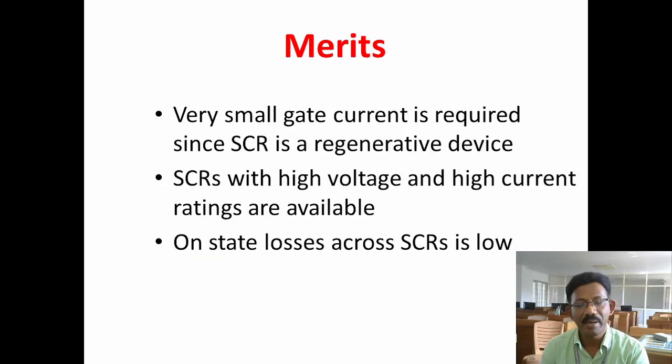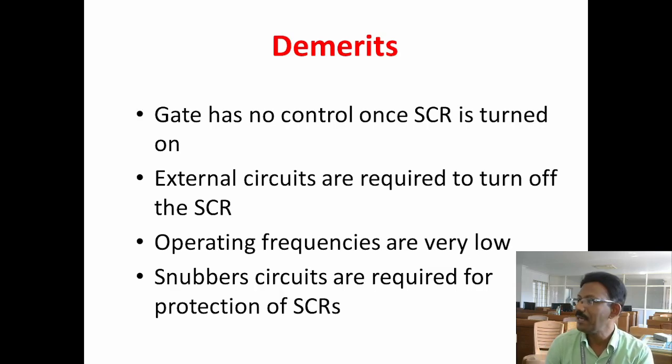Then let us see the merits of SCR. A very small gate current is required to turn on, since SCR is a regenerative device. That is one merit. Then SCRs with high voltage and high current ratings are available, so that we can use SCR in the power system side as well as in the heavy electrical side. Then on-state losses across SCR are low. These are the merits.